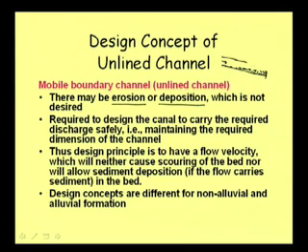When the slope is reducing, again depth is increasing, flow velocity is further decreasing, and then sediment deposition is further increasing. That way it is a progressive process, and that is why this is not desired at all. So, we should design the channel in a way that there should not be deposition of this kind.